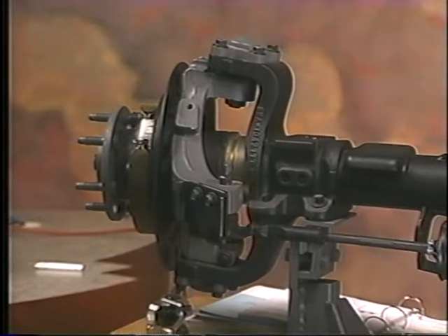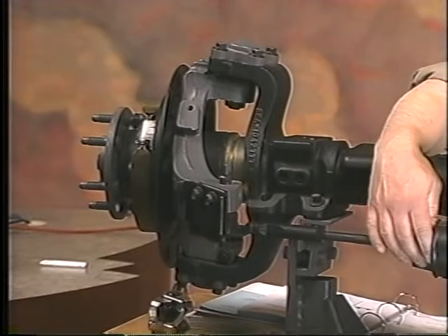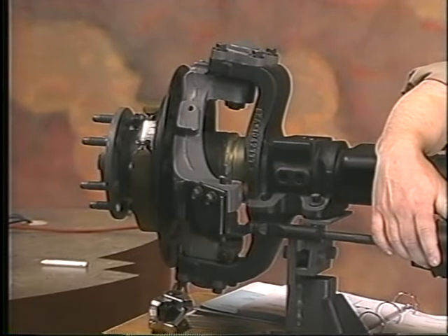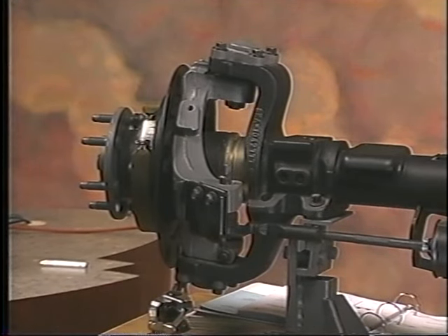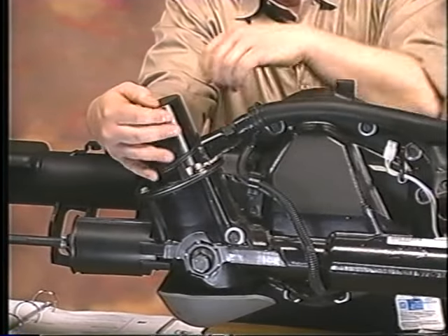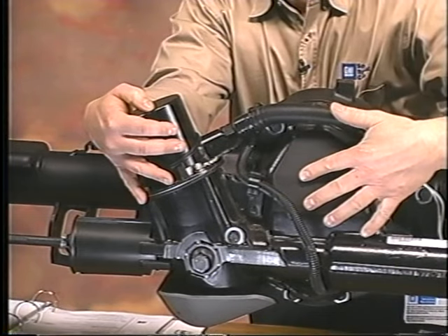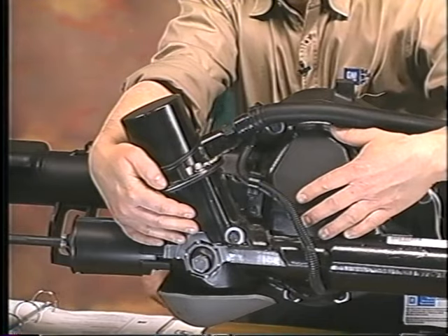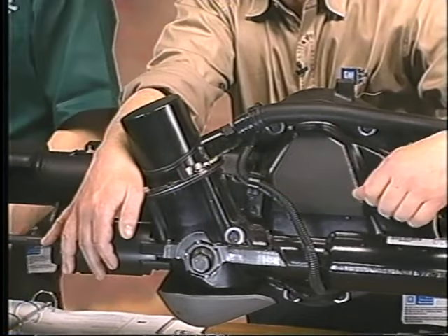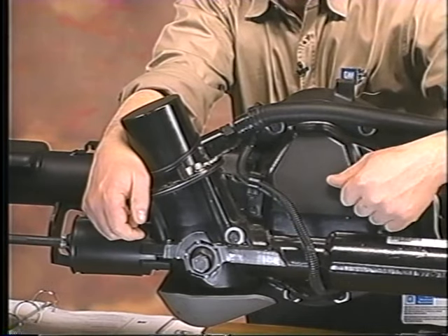What else we got? Well, we have tie rods. Okay? You can see. We got an outer tie rod here. As we start to move inward, we'll be able to see that we have an inner tie rod as well. Okay? Inside of the inner tie rod, now we get to the actuator. And the actuator's got a motor assembly. Also, see, all the assembly right here is part of the rear cover for our differential. Okay? So, if you have to replace the actuator assembly, you're going to be unbolting the rear cover to do that. You're going to be unplugging wiring, taking off our tie rod at the outer edge there, and then moving the whole assembly out of there. All right? So, some neat features there.